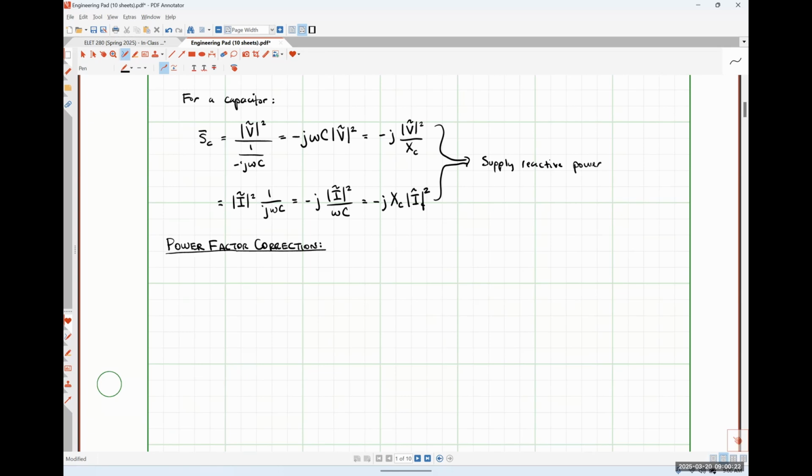When we talked about power factor in our last class meeting, I introduced it to you all as the ratio of the average power, which is what we as consumers pay for, to the apparent power, which is what the electrical utility pays to produce, okay? I also mentioned that quite obviously the electrical utility wants that ratio to be as close to 1 as possible so that they're not producing extra electricity that just winds up getting sent right back to them, okay?